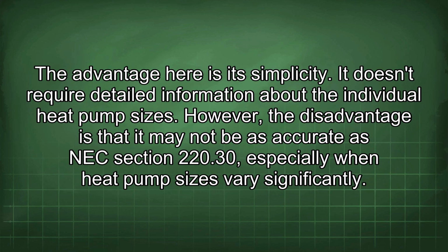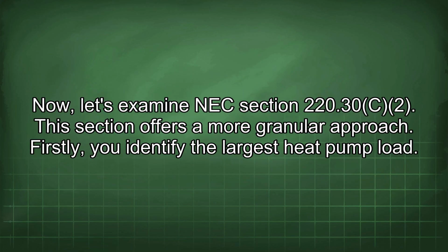The advantage here is its simplicity. It doesn't require detailed information about the individual heat pump sizes. However, the disadvantage is that it may not be as accurate as NEC section 220.30, especially when heat pump sizes vary significantly. Now, let's examine NEC section